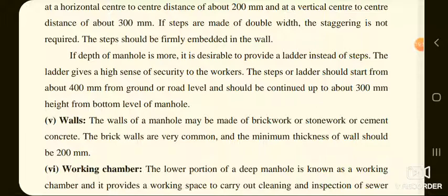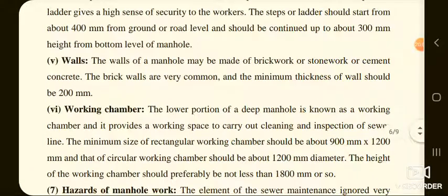The steps or ladder should start from about 400 mm from ground or road level and should be continued up to about 300 mm height from the bottom level of the manhole. Next component of a manhole is walls.